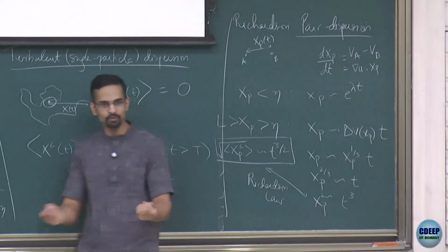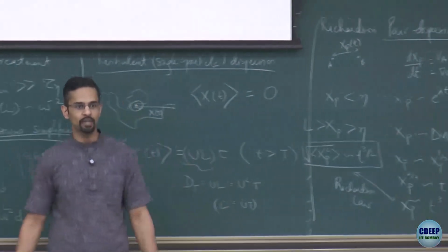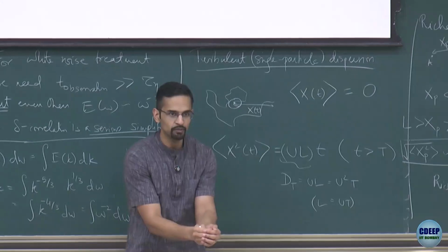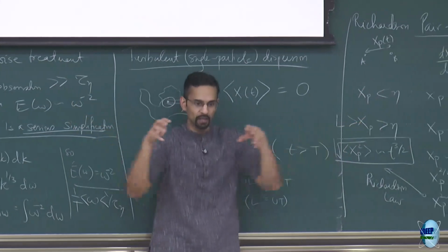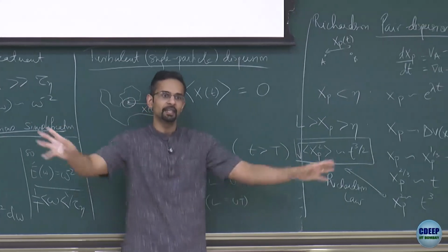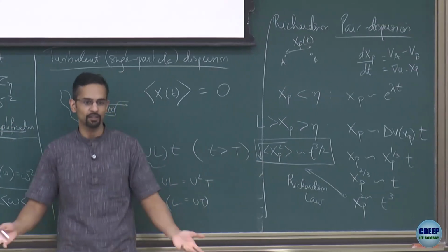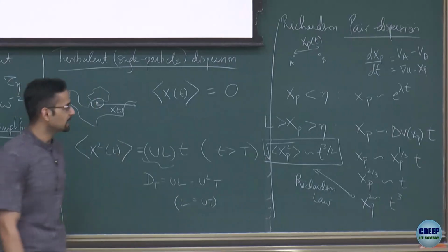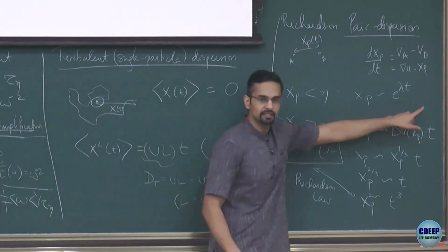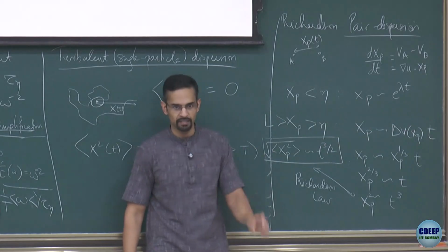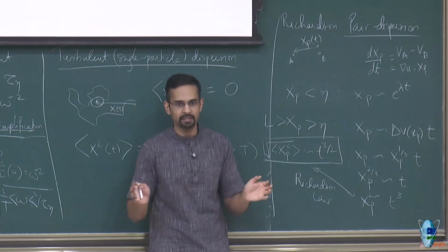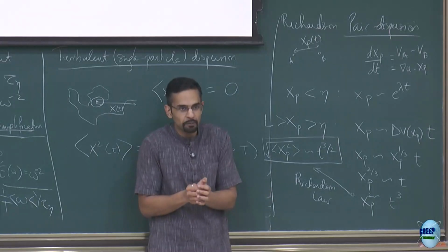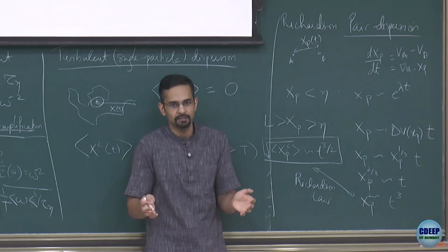So basically, this shows you that turbulence mixes things very fast, because if you start with a clump of stuff in the inertial range, it will spread out much faster than if you had taken the clump of material and sent it away at fixed velocity, which you would already think is fast. And that's definitely much faster than exponential at short times. At long times, exponential is very fast, but if you look at early time mixing, exponential means you separate very slowly when t is small.